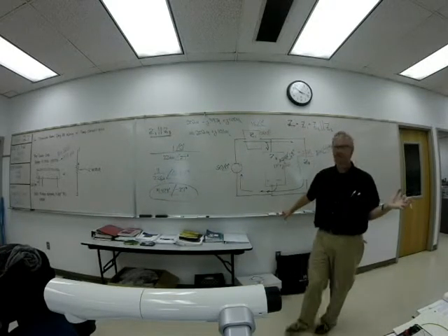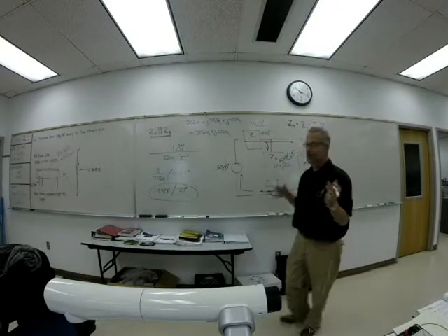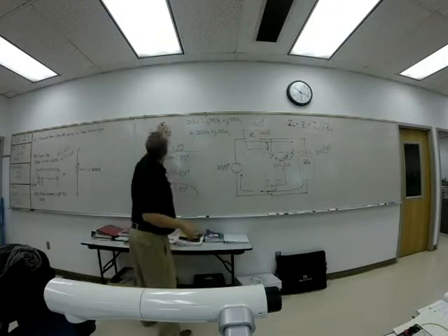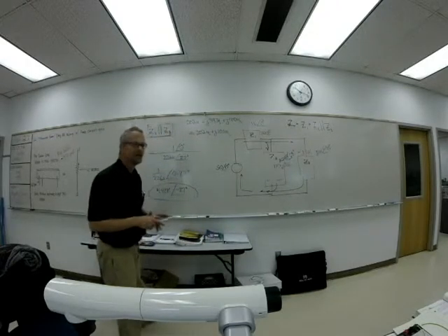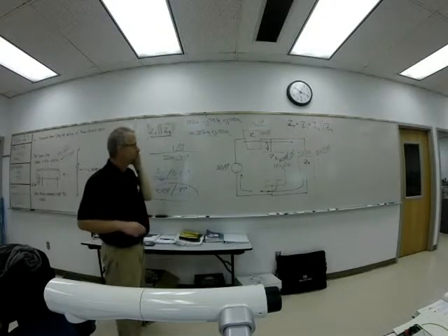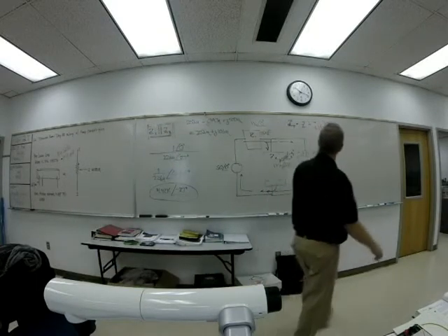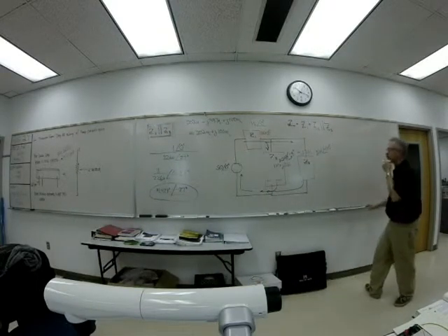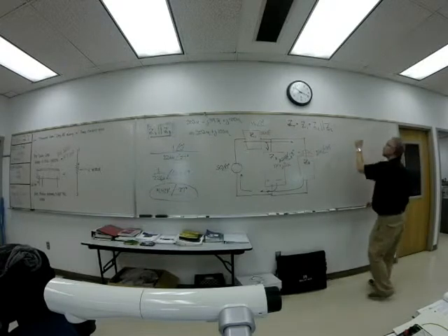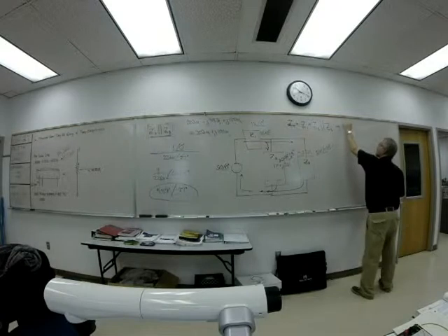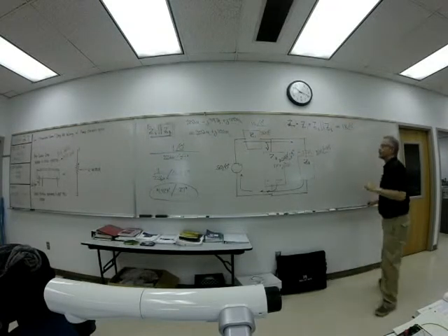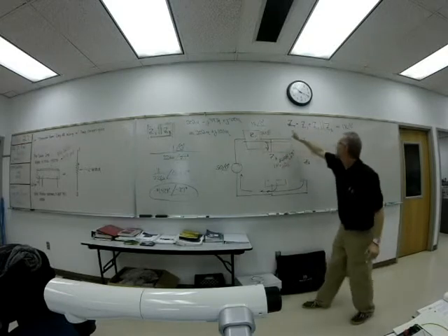We went down this road and we forgot where we started. What were we trying to calculate? Z2 in parallel with Z3. What is the total Z going to be? So you've got to add the 1K at an angle of 0 to that after you convert it to rectangular. 1K at an angle of 0 degrees, which is our resistance of Z1.